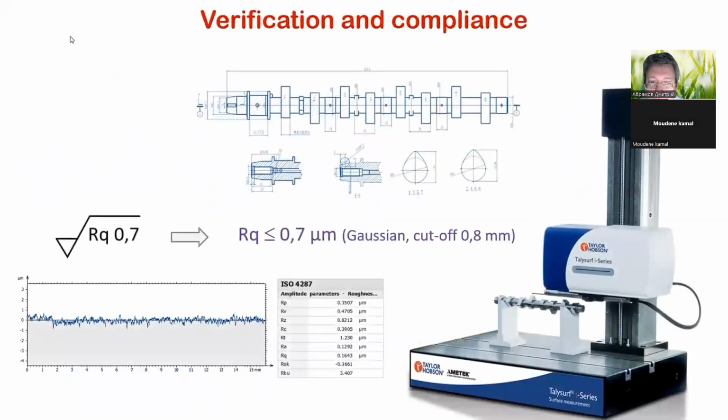The metrologist responsible for verifying a workpiece on a production line will sample some parts to measure them. He or she will rely on specifications written on the drawing and will use a profilometer or any other suitable means to measure profiles, or sometimes surfaces, and then calculate the surface texture parameters that are specified to finally compare their value to the tolerance limits.